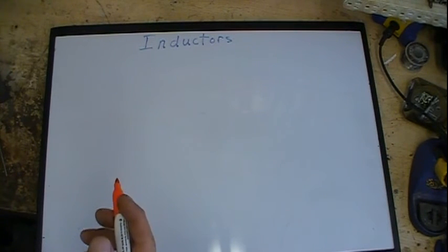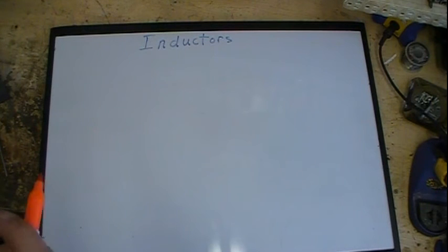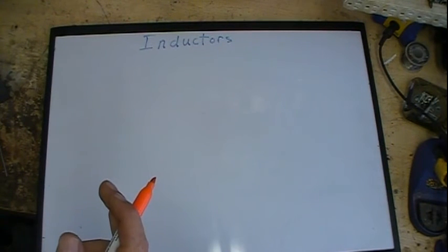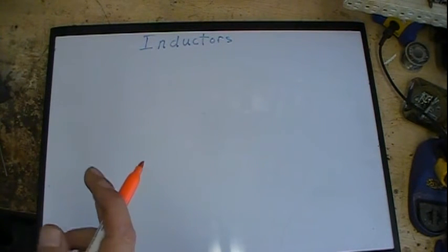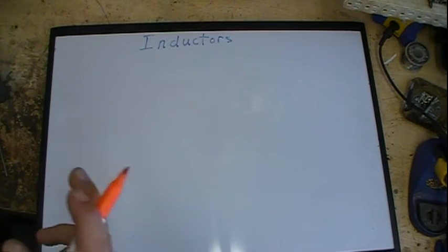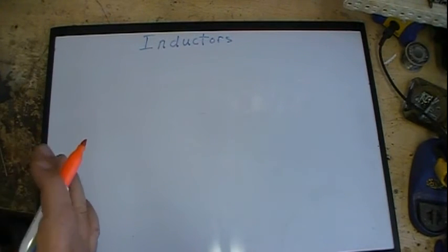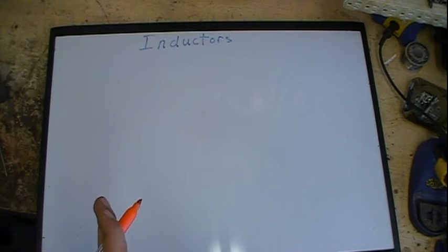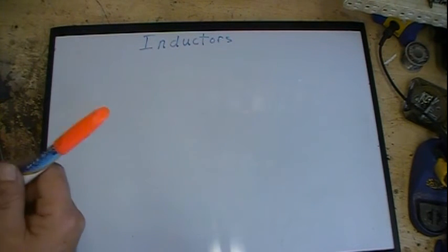Well, ELI is for inductors. E is voltage, I is current, L is inductance. So ELI basically is telling you the voltage leads the current by 90 degrees in a pure inductive circuit. So the phase angle will be 90 degrees if it's purely inductive.